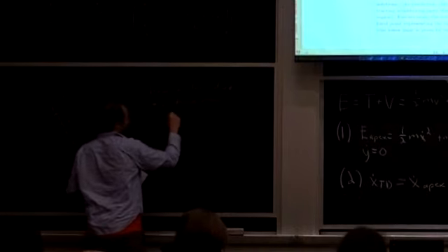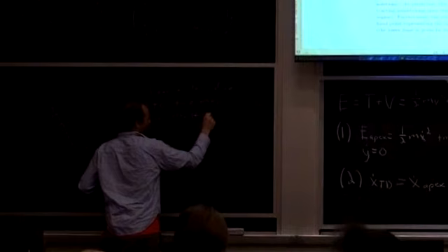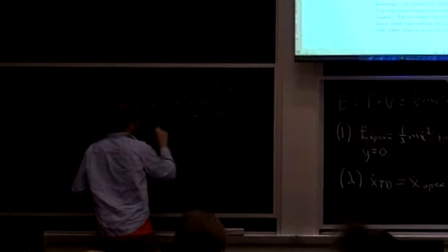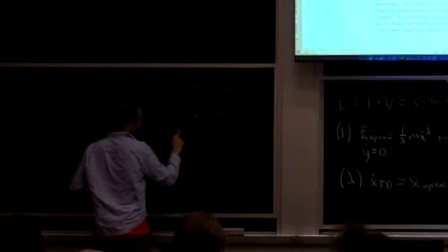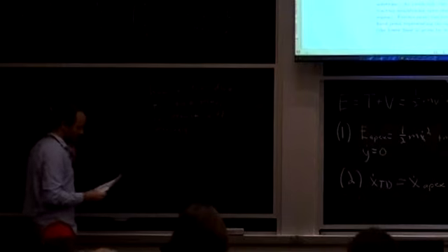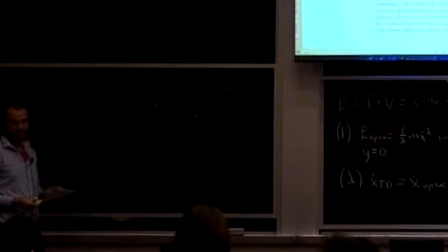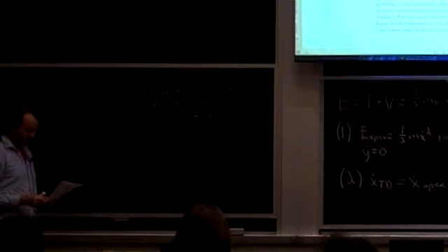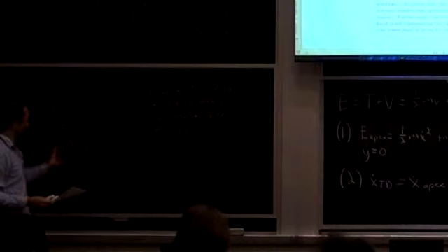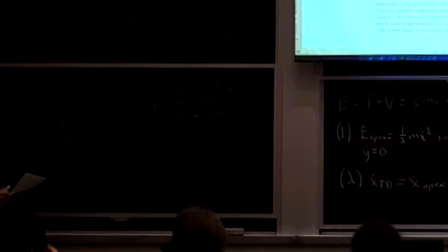So you must add energy. And they do this with a sort of control on the spring. If you can vary your spring constant like that, you can add energy to the system. And so the control on the spring is sort of their only control then. And you actually can get similar stability properties to the slip model. You can get these when you simulate it. You can find the same sort of stable fixed point, unstable fixed point kind of behavior.